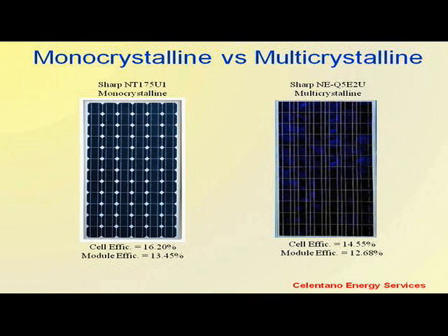The other difference is that with a monocrystalline panel, you will usually see these little diamonds between the cells. And the reason that there are diamonds between the cells is because of the nature of the silicon crystal, as it's made through the process I explained earlier, it comes from a cylinder. You could cut the cylinders into wafers. You get round wafers, and you could cut those round wafers into squares, but it would involve a great deal of waste. You'd be wasting crystal that was very expensive to produce.